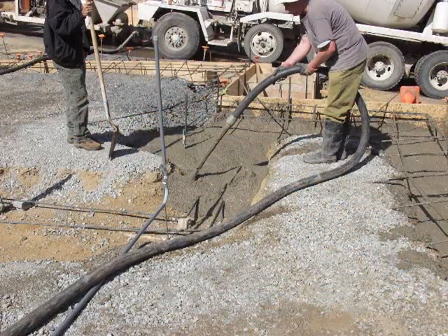So you can see here, the proper way to hold this hose is a little bit further back than right up front. If you hold it right up front, it's going to jerk you around quite a bit. So if you can hold it back a little ways, you'll get a better grip on it, and you'll actually have more control of it. And by holding it this way, you can place the mud right next to you, or you can actually project the mud quite a distance away from you.